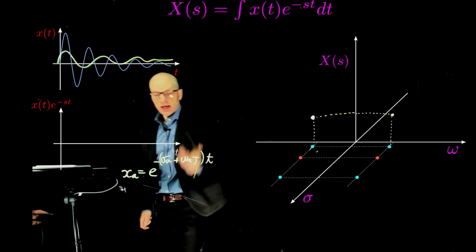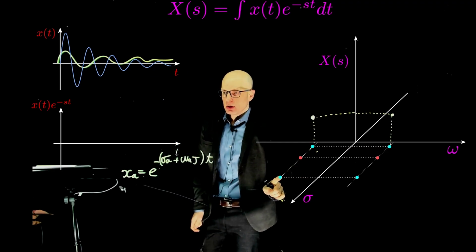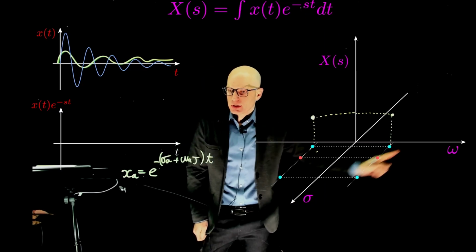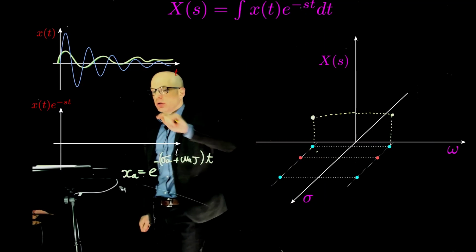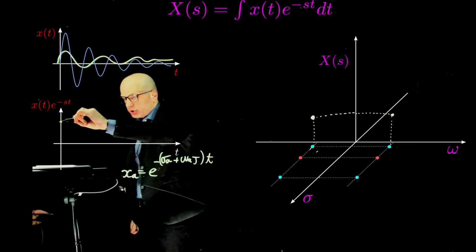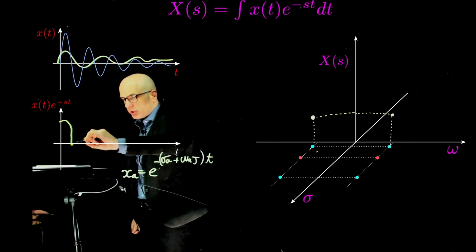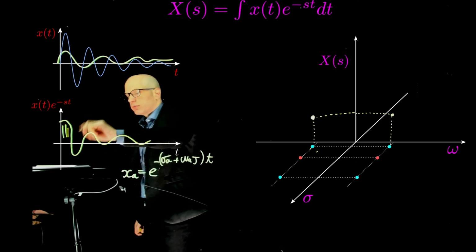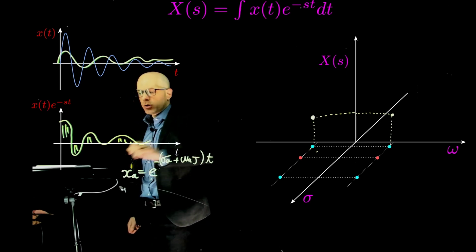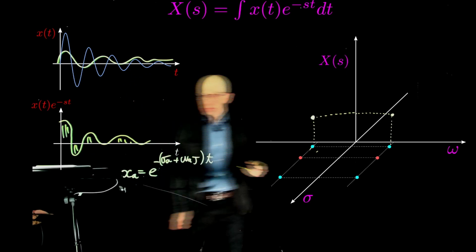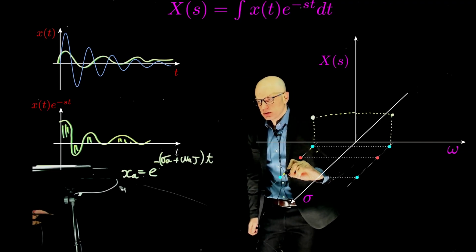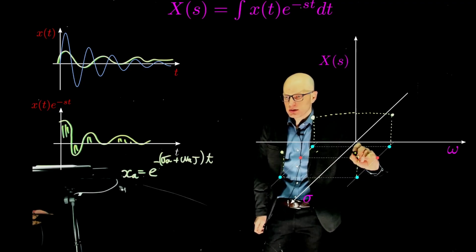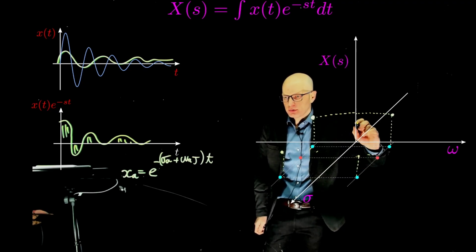Again, we can now take the signal we created through this point here. That's exponential of negative s t, where s is sigma plus j omega. That's the signal. We multiply them. Same story again: portions of this multiplication are positive, portions of this multiplication are negative, and so on. You take the integral, this plus that, and so on. Because there are negative portions, we'll have the same effect. The result of this operation will be a finite number of no particular interest. This is the magnitude of that operation.